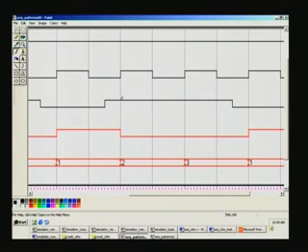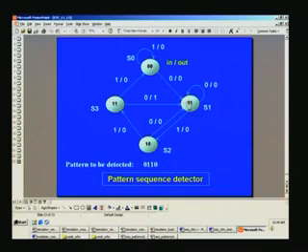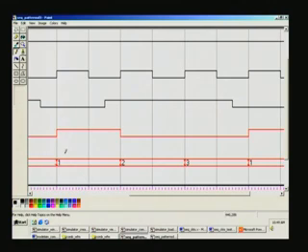So, now you will be sensing 1 for the input in state 1. So, let us have a look. In state 1 if it is 1, it should take you to S2 here. So, we had gone to and fro earlier, we are coming back, right. So, that is what it is.